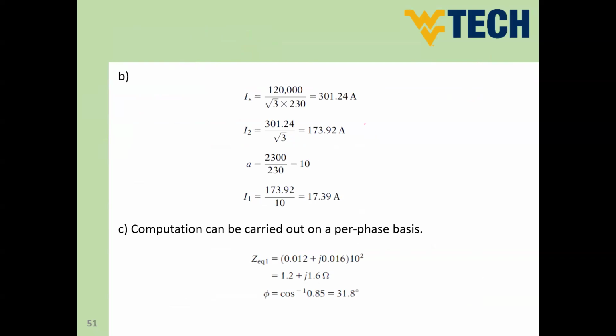You know that we supply a load of S equals 120 kVA, and the voltage of the load, V load, equals 230 volts. It's connected as a delta connection. So simply you can say for a delta connected load, the general relation of power is S equals root 3 V line I line, and you have V line equals 230. So simply we can get the I line.